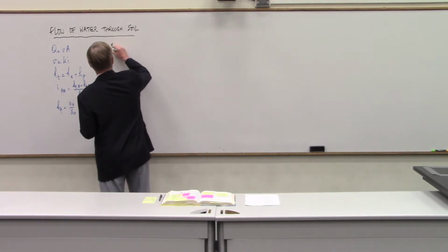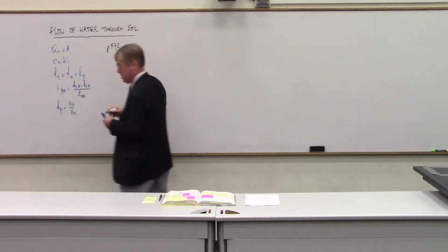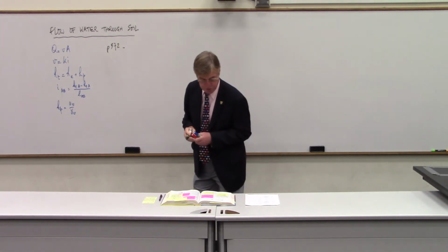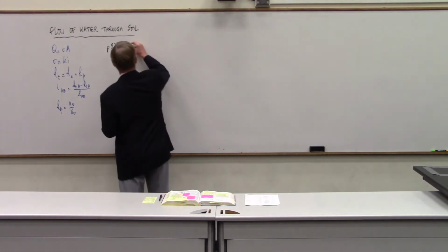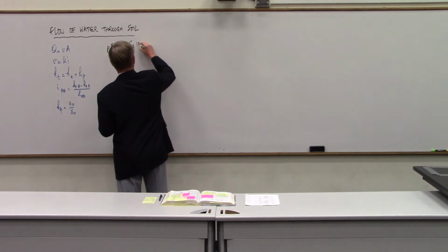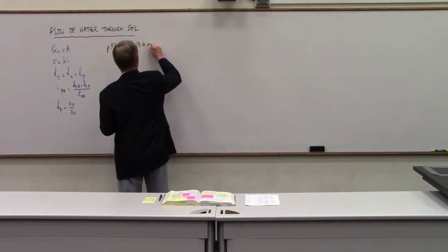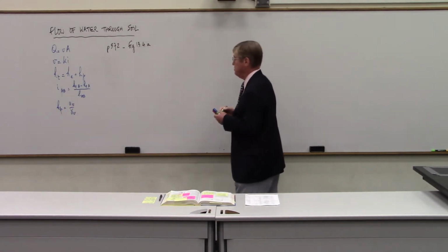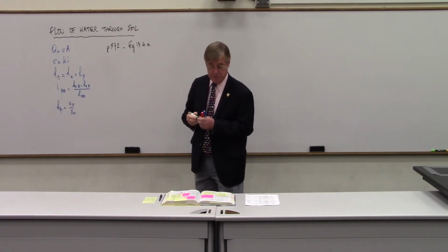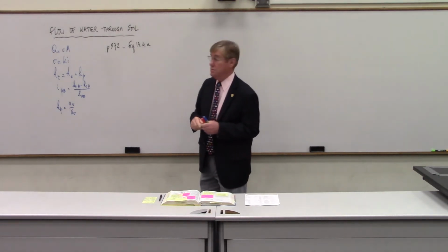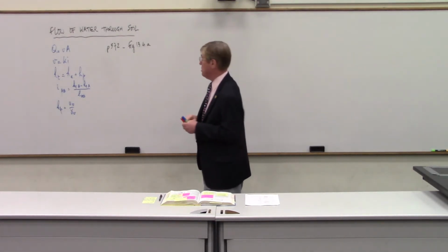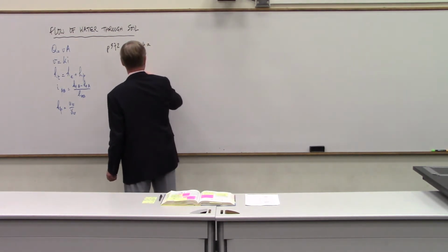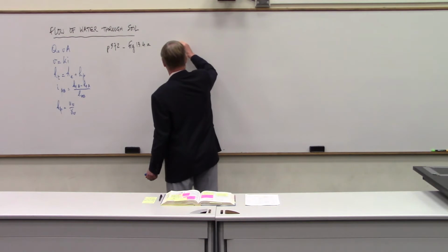Page 372, and we're going to do together the diagram in figure 13.4.8. The diagram, so this is a constant head permeameter, like the one you're doing in the lab to measure the permeability. And here is, let me reproduce this diagram.